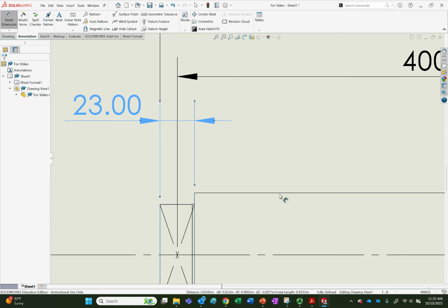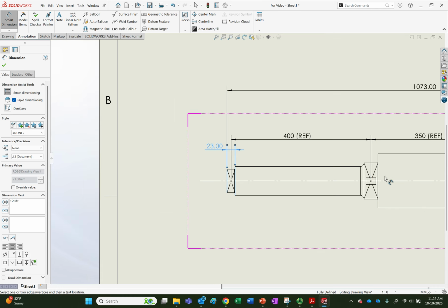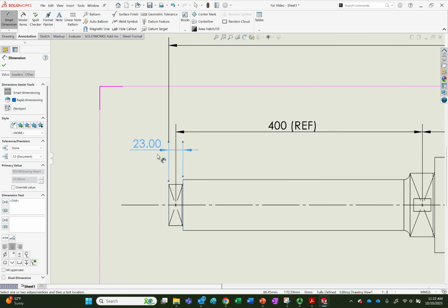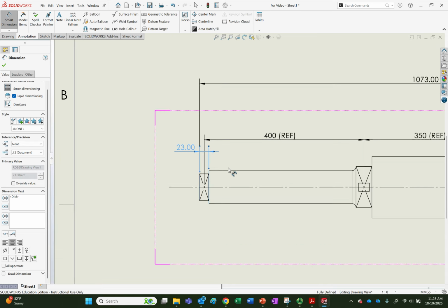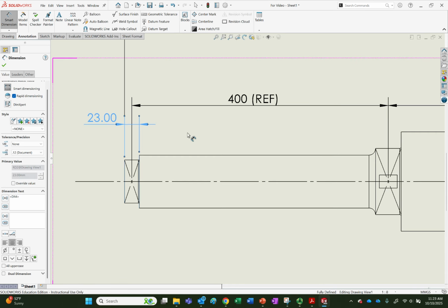All right, so here's a 23. If I was using US units, and I know that this is 23 millimeters, but in US units it would have converted into inches, I would have also put a secondary dimension, a dual dimension down below, which would have given the metric one. So I can let people know, because you go like, well, you give it 0.9 whatever inches, and you don't necessarily know that it's 23, that it just happens to convert to that. So it's good to give the dual dimension to let them know that's what you were doing.